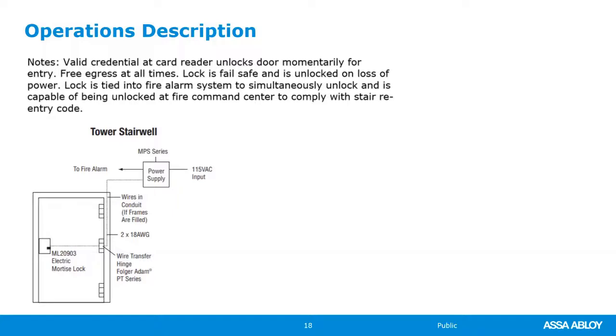The outside handle is locked and unlocked by the cylinder. That comes from ANSI BHMA, the standard. A storeroom function lock set, no matter what manufacturer, if I specify a storeroom function lock set, the outside handle is always locked, the key will retract the latch, and the inside is free for egress all the time. Those come from ANSI BHMA, and those are standards for mechanical locking functions.